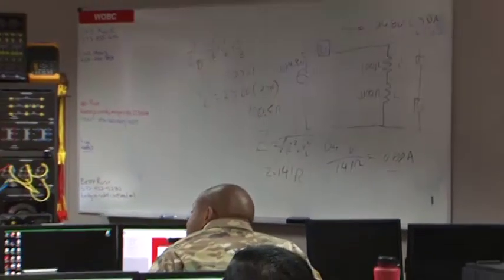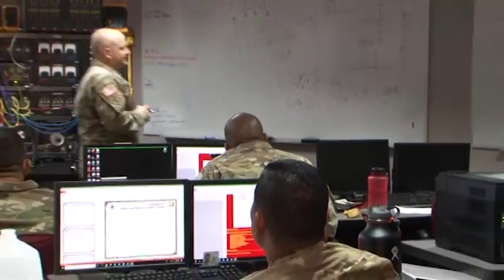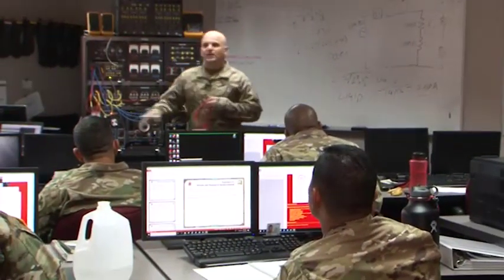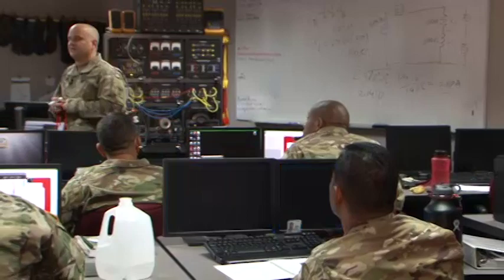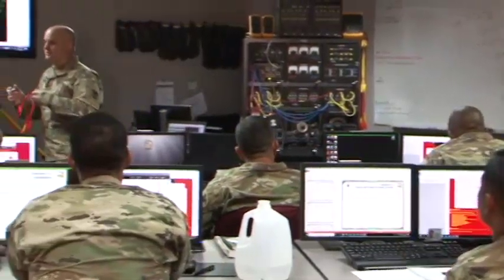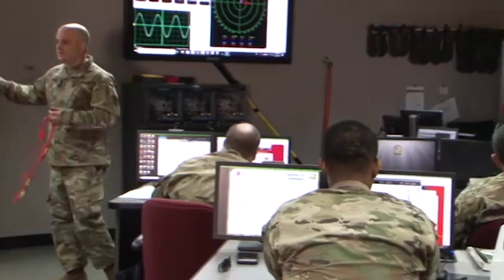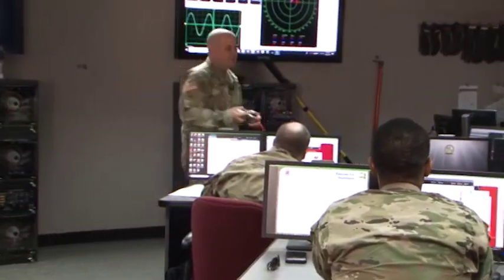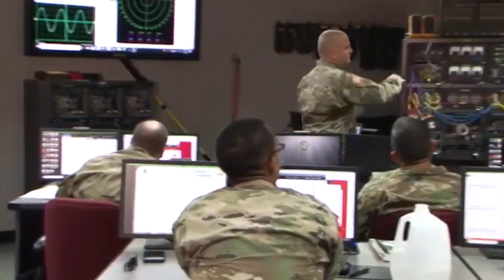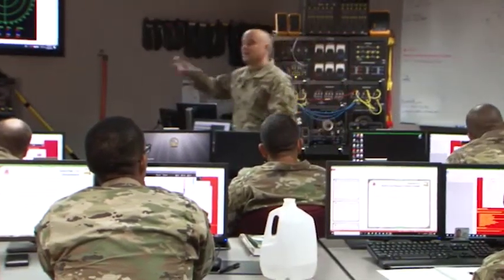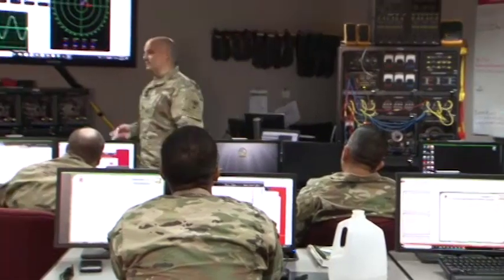Now, the difference, and I'll show you that here in a second, I'm going to set up a parallel circuit, and we're not going to use that same formula for impedance because just like in resistance, where we see the relationship between equivalent resistance in circuits, we're using some inverses going on in there. Same thing applies to the impedance in a circuit, so if we were going to solve for the same two things in an RL circuit that's parallel, we're going to use a different impedance formula.